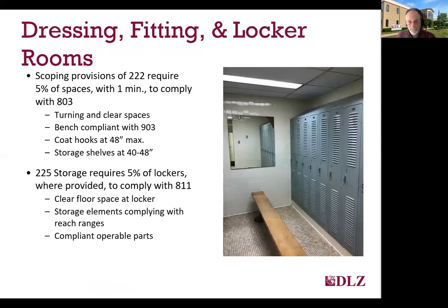So dressing, fitting, and locker rooms are addressed in the scoping provisions of section 222, which requires that 5%, with a minimum of 1, of all dressing, fitting, and locker rooms be compliant with 803. Quite often in municipal facilities, these include primarily locker rooms that are integrated into spaces with restrooms and showers. But 803 also requires a bench that complies with the technical provisions of 903 and requirements for coat hooks and storage shelves. Section 225 of scoping, entitled Storage, requires 5% of lockers to comply with technical provisions of 811,